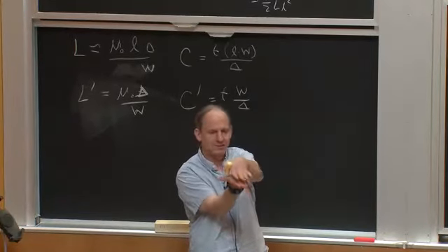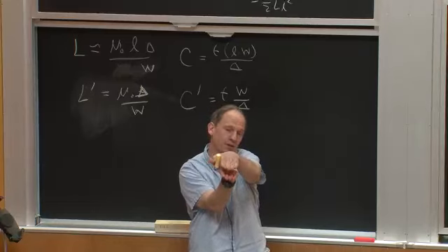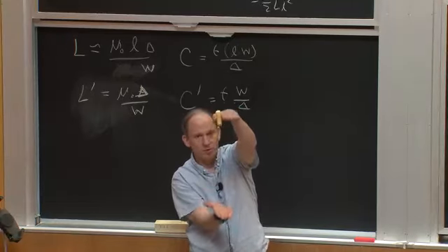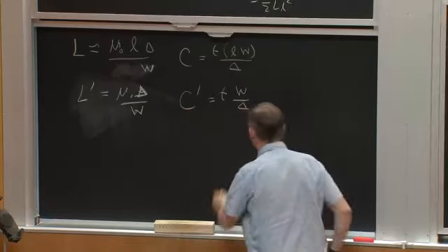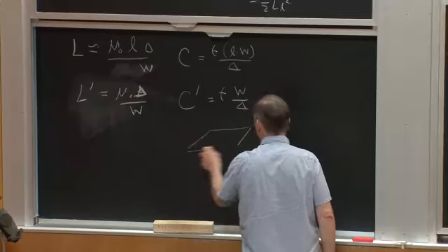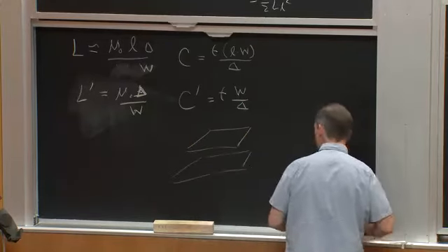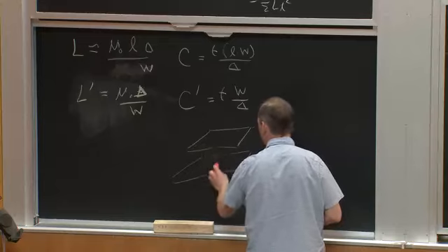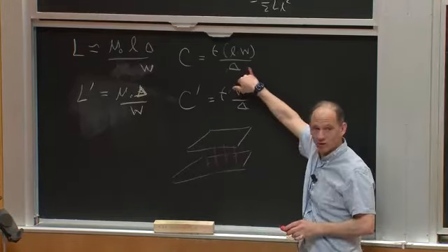Or in a capacitance, if I have two pieces of metal that are of the same size and they're really close together, that's a pretty good approximation. When I start to pull them apart, what happens? Well, in the capacitance case, this approximation is really just capturing the fields that are directly between these plates. That's how you get to this equation.